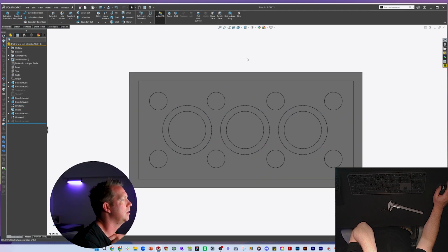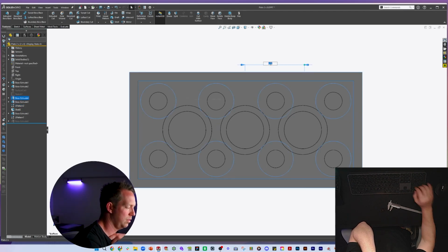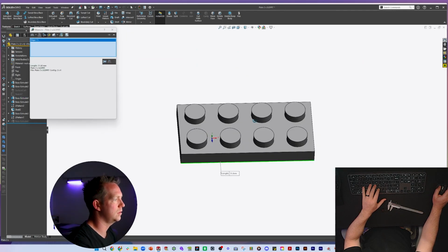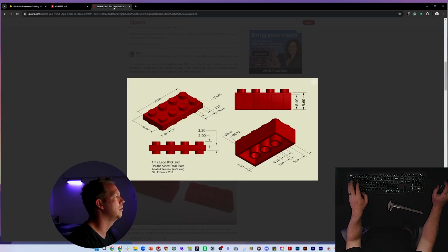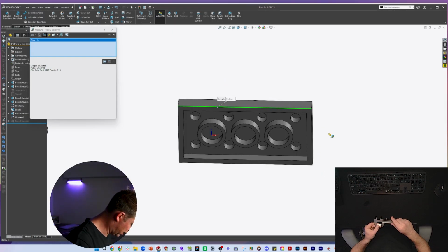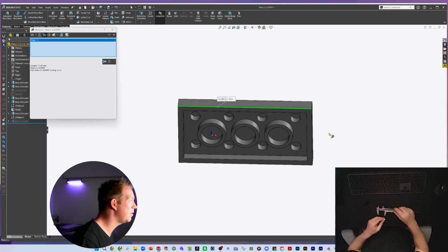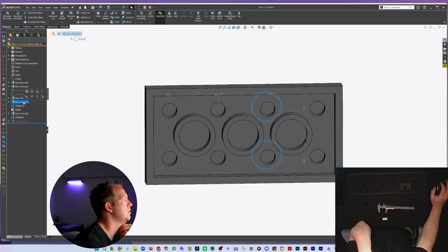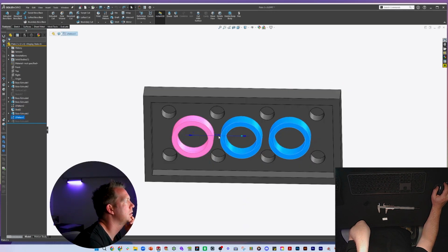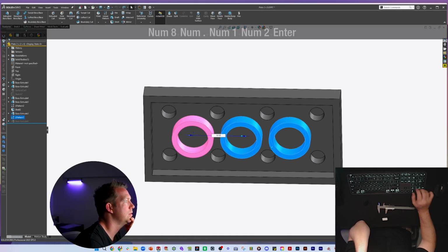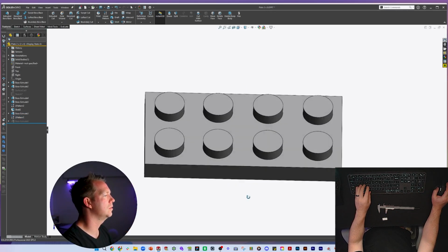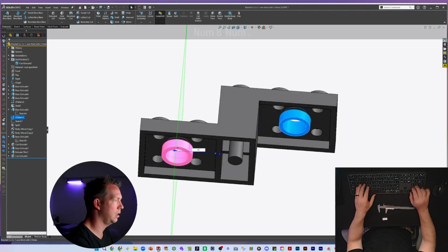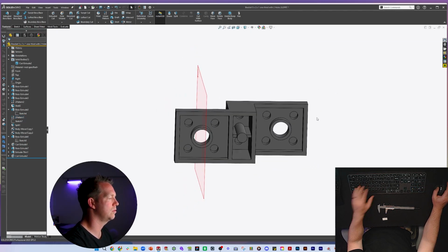I think yes. And this one, 7.9, it could be causing ourselves a few issues, because that's our 4 slot, 31.6, 31.9, because we're not allowing for the clearance. Yeah, it's 31.9. Okay, so we need to adjust. If that's going to be 8.12, could be fair enough. Should be 8.12 as well. I think that's all it needs. I think that makes sense. So this here, 8.12, and now that should be central.